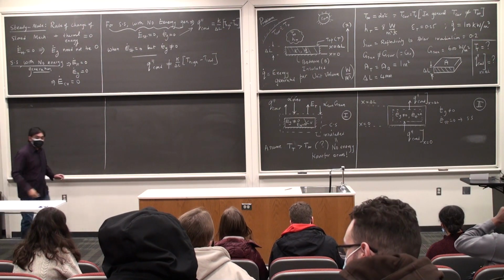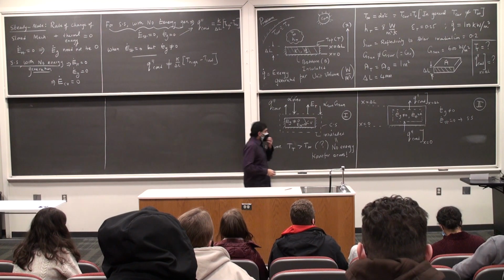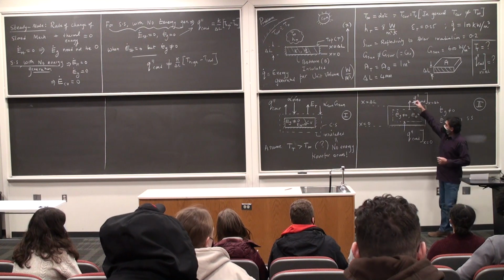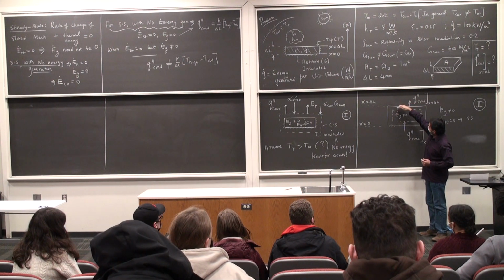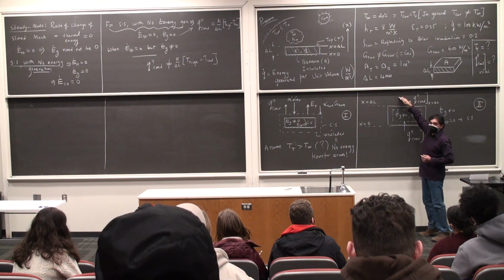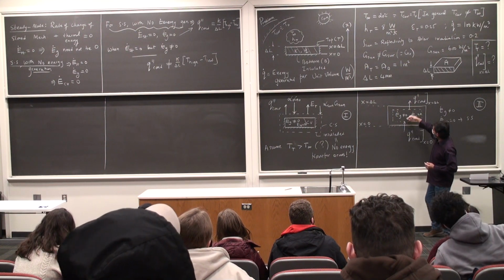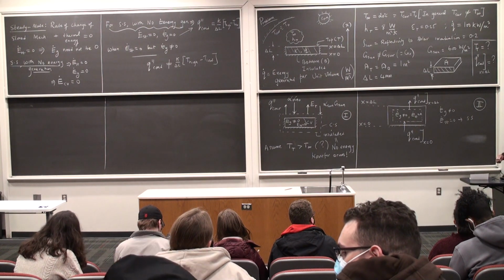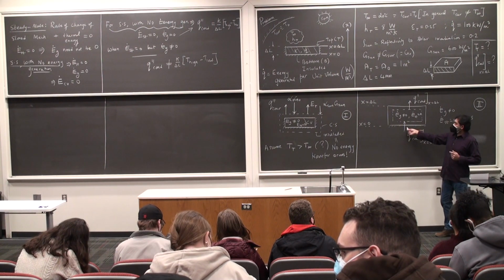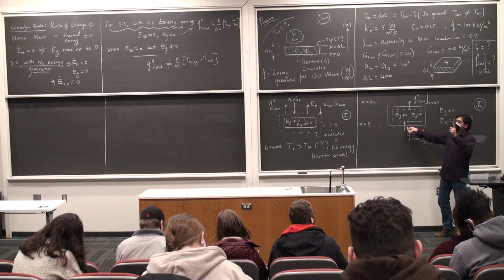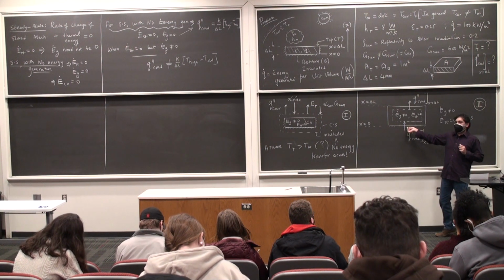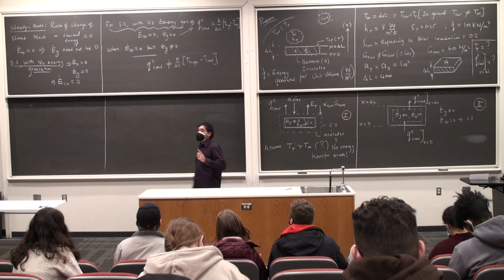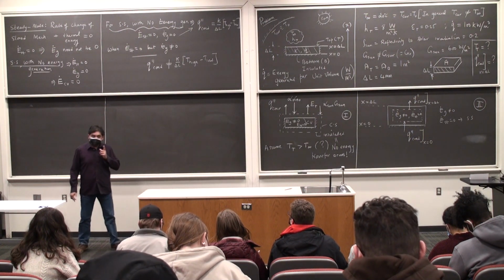Could you put those signs reversed? Does this still work like the last situation? It could. But if I'm assuming that the direction of heat transfer from convection is from here to there, then it kind of implies that the conduction is going to take place from the bottom to the top. If I reverse it, then things will be different. I'm completely free to assume what this direction is. The math will tell me whether I'm right or not. So one thing you want to remember, this is something I always tell people, don't trust your intuition, trust only the math.